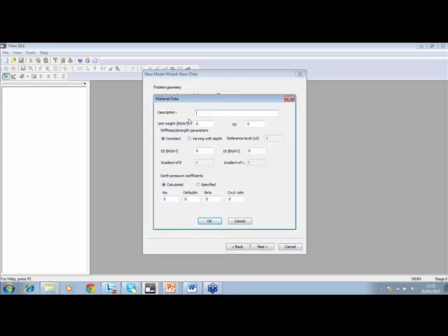We're going to add glacial till, unit weight 21, K0 of 1.5. We've got a constant stiffness with depth. We've got a stronger material here, Young's modulus of 45,000. Again, specified earth pressure coefficients of 0.3, 5, 1, and 1. Okay, and finally, I'm just going to add the sand and gravel.